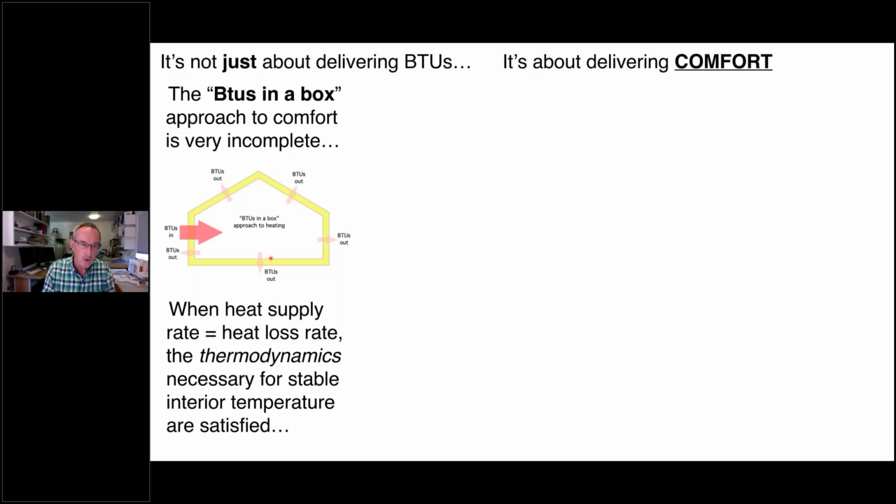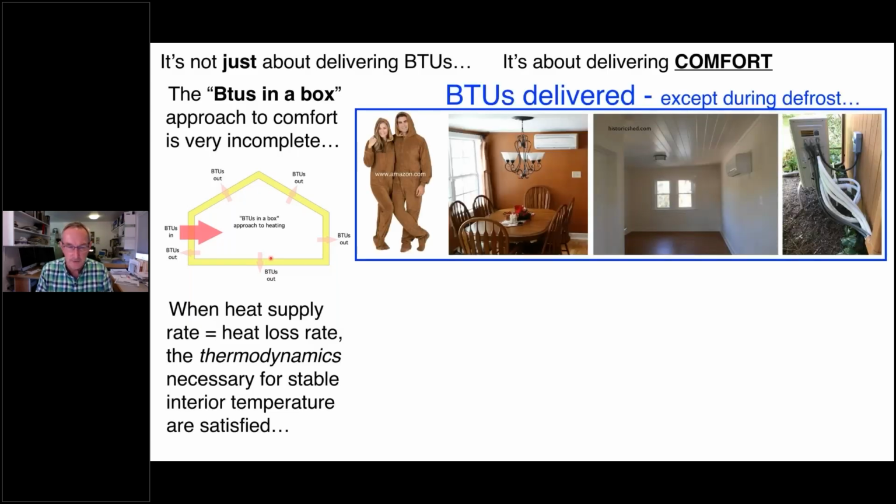We want low noise. So I have this concept I call BTUs delivered, except during defrost. The photos show some ductless mini split systems. They can be sized so that they're capable of delivering BTUs into the space equal to the rate of heat loss, and the BTUs come in the form of a forced airstream coming out the bottom of one of these wall cassettes. Is that all you need for comfort? My argument would be no, it's not.